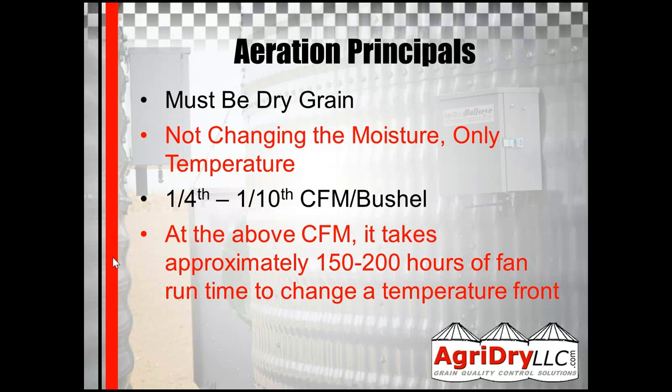So now when it comes to the aeration principles, the guys that are mainly just changing temperature, you're going into the bins at the right moisture already. You're not trying to change the moisture. You're just trying to take the temperature in and out of the grain, store that grain. This is the aeration principle. So the grain must be dry typically. We don't want any wet grain in there that you have to change the moisture, because if the bin is set up for aeration principles, you have a lot less airflow, meaning less horsepower, less electricity that you have to burn. So you're not changing the moisture, only temperature.